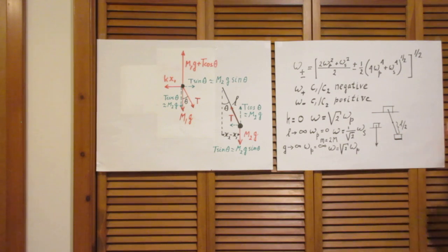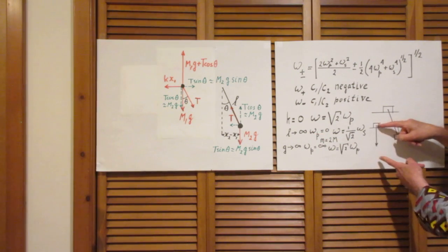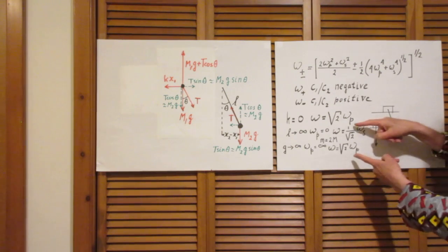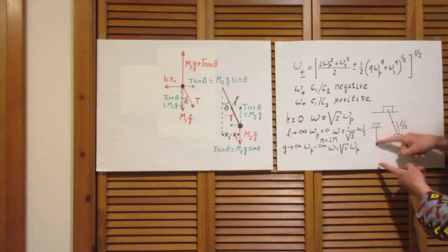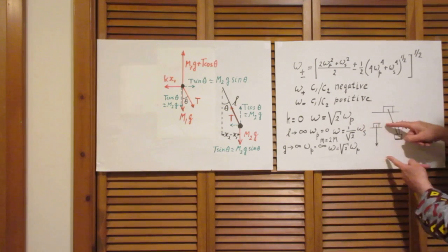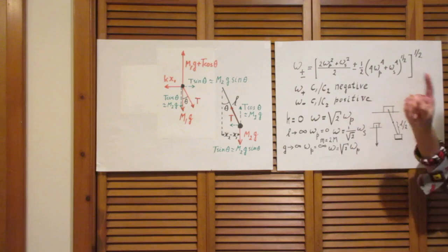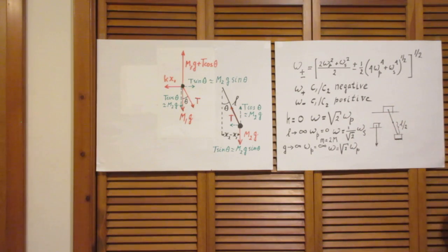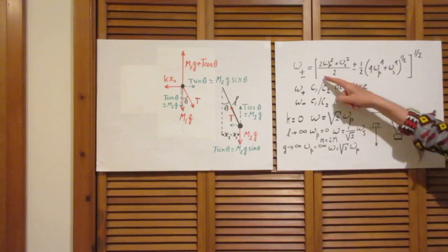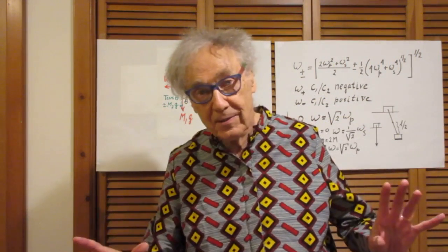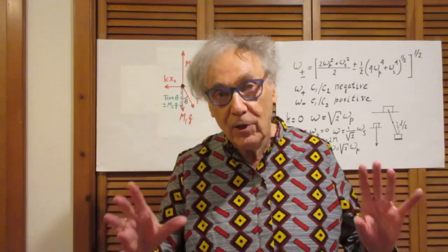And in the case that I make L equals infinitely long, I can really see that the spring is now acting on 2 masses, which will always stay vertically above each other. And therefore I must now find one frequency which is 1 over the square root of 2 times omega s. If I don't find that, this is wrong. So consistency checks are always very useful.